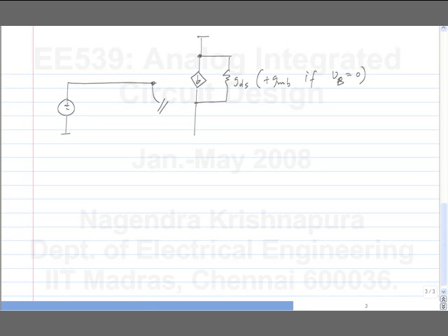So predominantly there are two capacitors. I will call this CGS, and this represents the source bulk junction capacitance as well as any other capacitance that you explicitly have as a load. So this is a voltage buffer. You use this to drive either small resistances or large capacitances. So you can have a case where there is a substantial amount of load capacitance applied to the source follower. Gate to ground, yeah. So we'll also have this CGD.